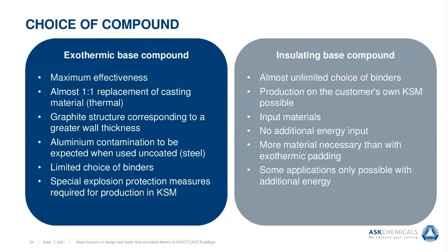Also, you are limited in the choice of binders because the exothermic material has some components which may react with some other components in some binders, but we will come to this issue later. And of course, if you want to produce an exothermic padding in your core shooter, you also have to consider explosion protection measures and other safety issues. But we can help you here if you have any questions about what you need to realize that.